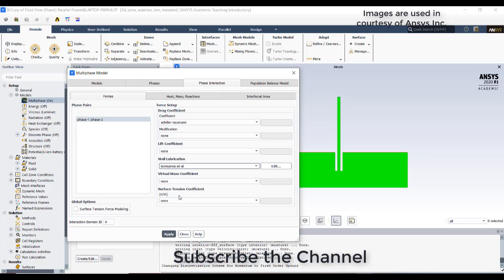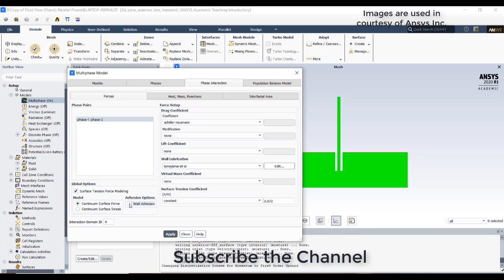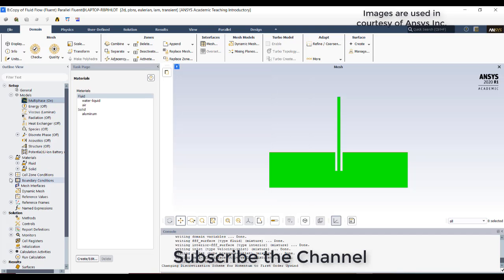And the surface tension coefficient is important. The constant value is 0.072. Surface tension modeling is very much important. For wall adhesion, what angle do you want to give? So select wall adhesion, apply, and then just close it and go to boundary conditions.